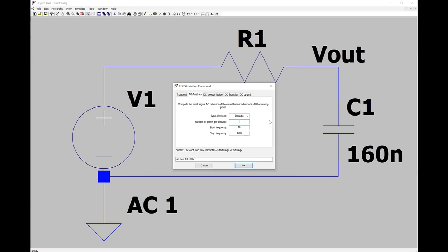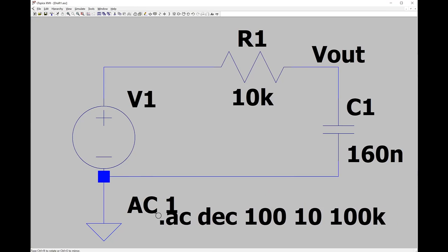This harkens back to when I was an undergraduate, and computation on these things might take an hour. Now it takes fractions of a second. So we can easily say, plot 100 or more points per decade. So between 10 hertz and 100 hertz, plot essentially 100 of these phasor analyses, and then do the same between 100 hertz and 1,000 hertz. And computation is cheap now. So here's our command to do all that plotting.